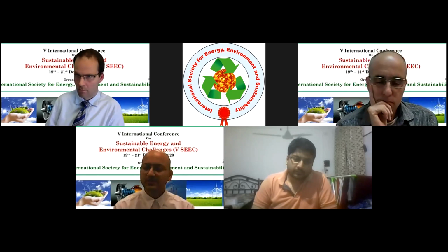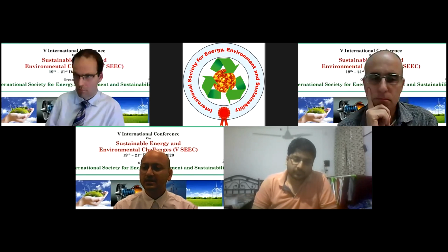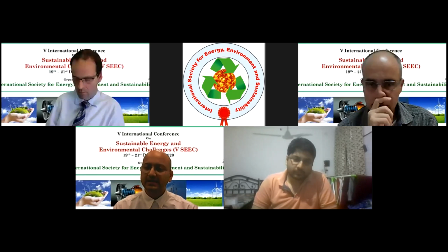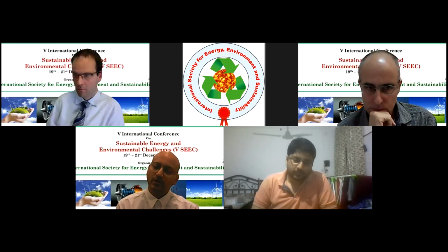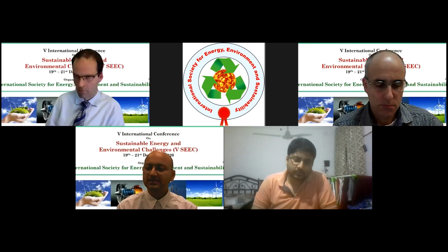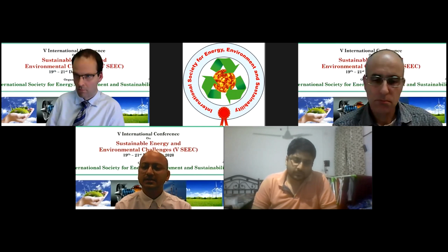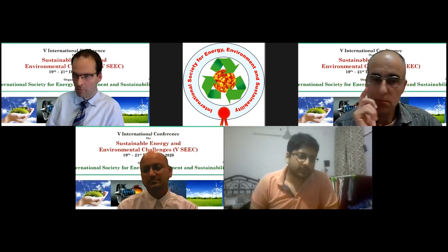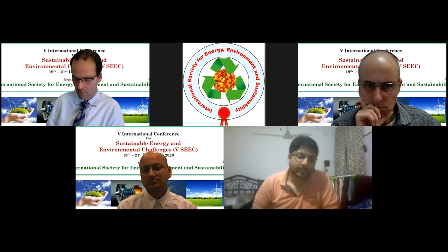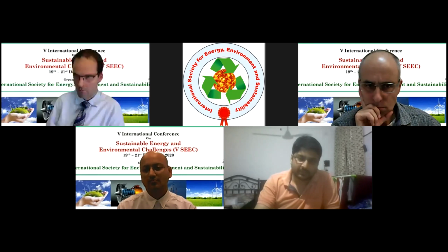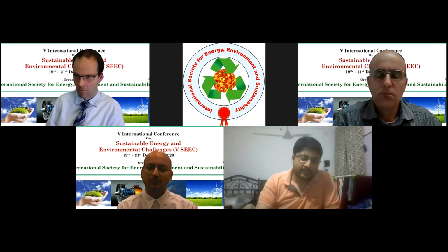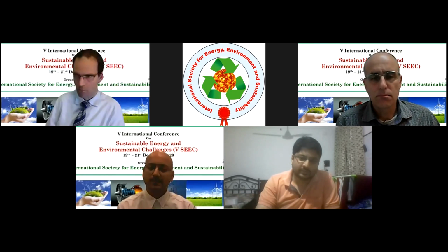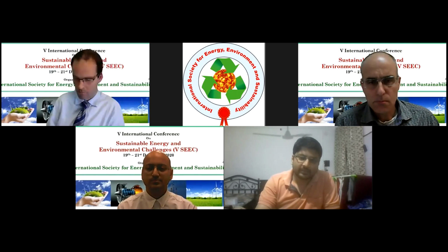Thank you, Professor Nawaz. I think another question is, what happens if we inject this RO concentrate deep down into the water table? Of course, alkalinity will increase, because carbonates are there. Also, calcium salts and magnesium salts are increasing, so it will increase the hardness.